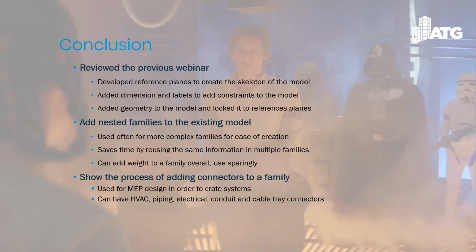So again, in conclusion, we went through a little bit about the previous webinar, on the reference planes, to create the skeleton shape of the model, add dimensions and labels, and then add geometry and lock it in. Also, in the first part of the session, I went through nested families. They can be used to create more complex families.